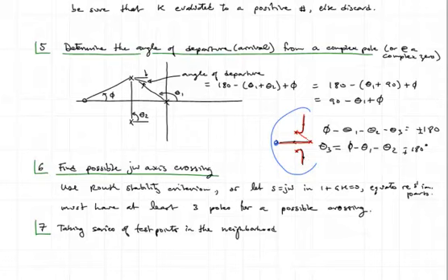You'll notice the angle of departure here is going to be important, especially when you're close to the j omega axis, because that might indicate whether or not that root locus branch is going to cross the j omega axis, or at least whether it will get close or move closer to the j omega axis, thus making the system less stable.